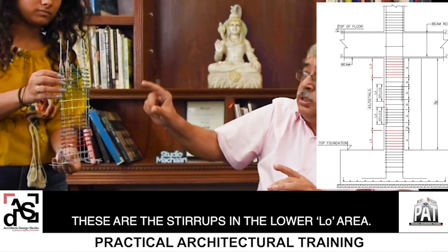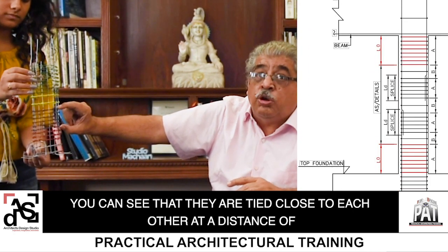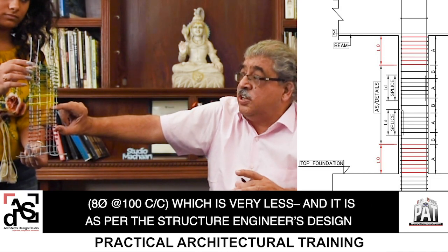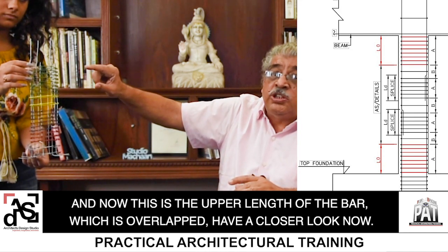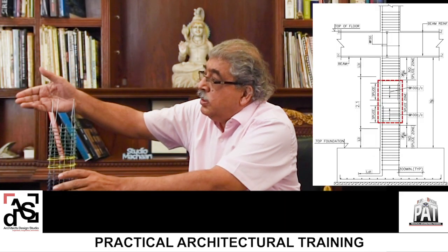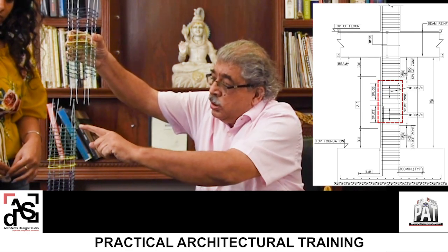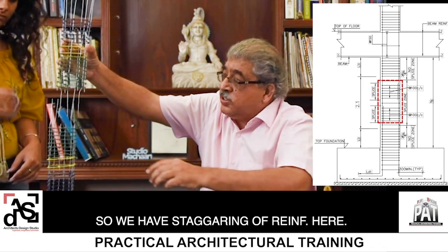These are the stirrups in the lower LO area. You can see that they are tied close to each other at a distance which is very, very less, and it is as per the structural engineer design. And now this is the upper length of the bar which is overlapped. Have a closer look now. So this is the upper overlap, and again they are staggered because this is going to meet this area and this is going to meet this area. So you have staggering of reinforcement here.